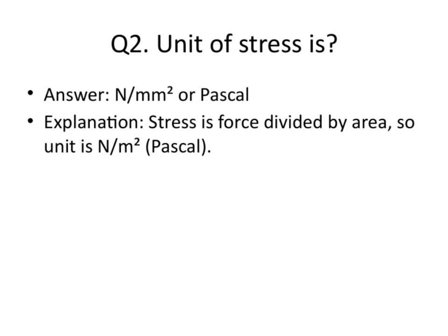The answer to this question is N per square millimeter or Pascal. Now, let's understand why that is. Stress is essentially the force applied over a specific area. So, when you think about the units, force is measured in newtons, and area is measured in square meters. Therefore, the unit of stress becomes newtons per square meter, which we call Pascal.